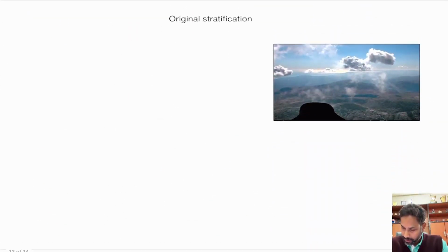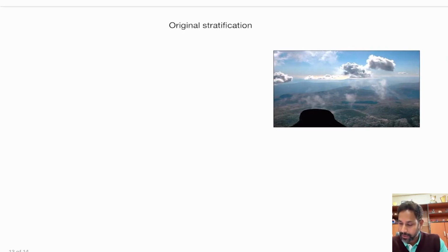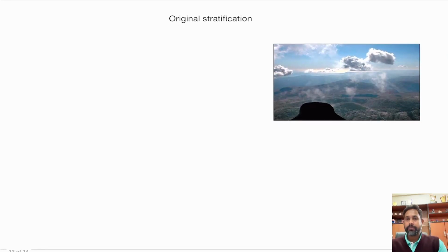And now we have to talk about the stratification that is there in the system. So what happens is, let's consider before convection begins, right, before the day starts or before the summer starts, there is usually stratification in the medium. So if you measure from the bottom, this density of the fluid is actually, or temperature, let's talk about the temperature generally increases as you go up. So if T naught is the surface temperature